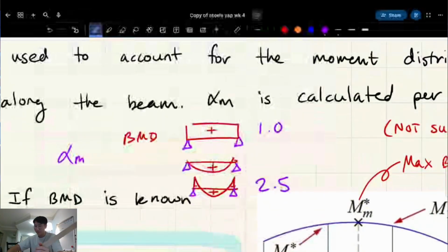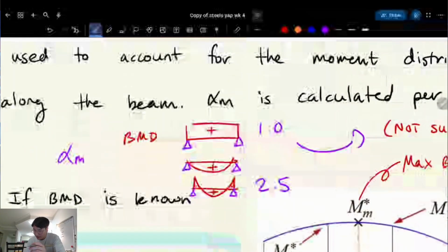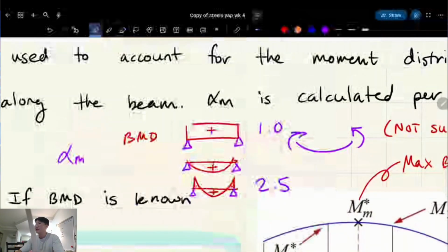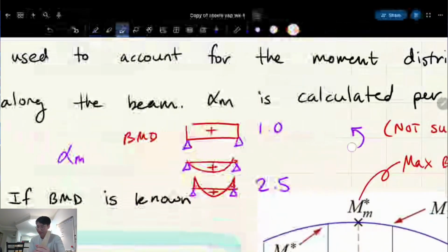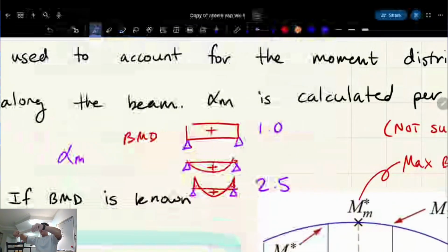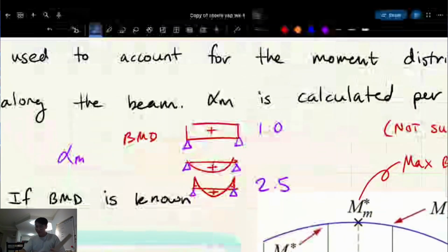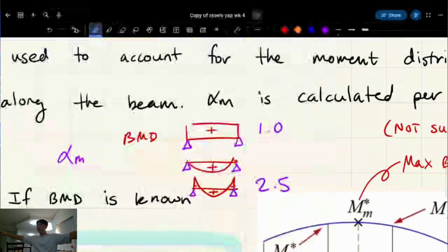Yeah. That's the worst one, because when I talk about racking, I'm talking about how I was bending that stick as if it was a point moment on both sides, and that creates that straight bending moment diagram, right? That flat bending moment diagram. That's the worst, because the moment has nowhere to go, basically. It has nowhere to spread out throughout the beam. But for the other 2 cases, it can go to the edges. It can redistribute, so it's the moment redistribution factor, pretty much. Does that make sense?